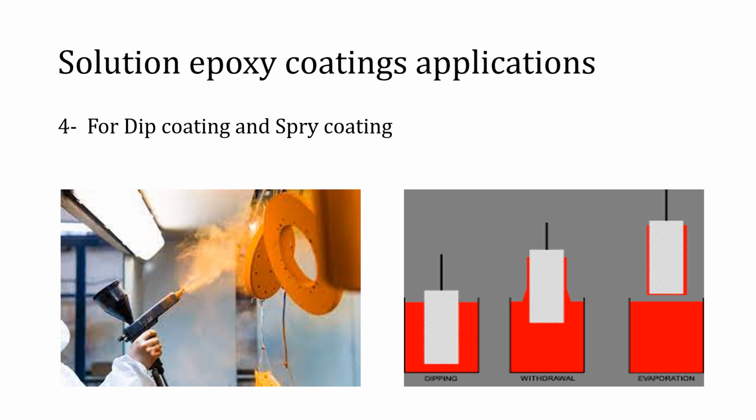In addition, in continuous dip coating applications, the system is open and evaporation of the solvent, which affects the concentration of epoxy formulation, is an issue. For successful dip coating application, it is important to minimize solvent evaporation by employing a proper tank design. Moreover, there should be no reaction between the coating solution and the material with which the tank has been made of. Other important factors in dip coating include the desired coating thickness, temperature control, anti-contamination measures, degree of agitation, dipping and withdrawal speed of the object, etc.